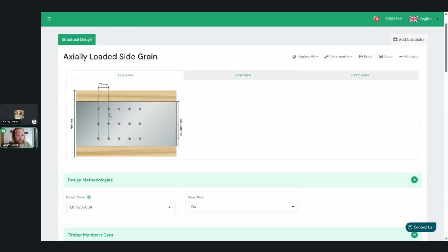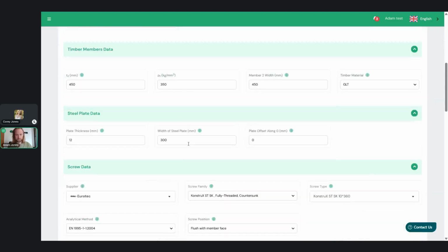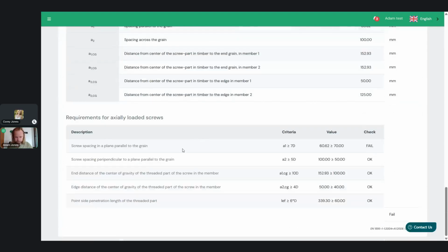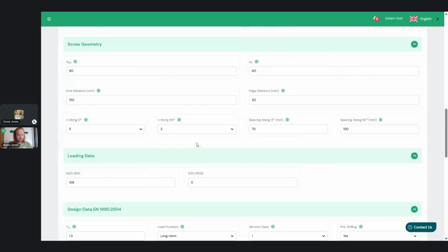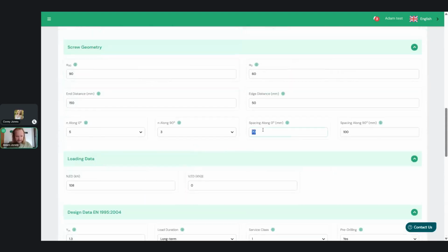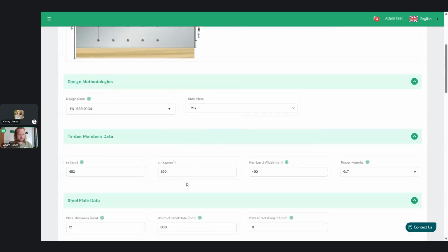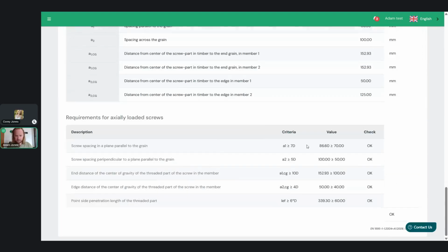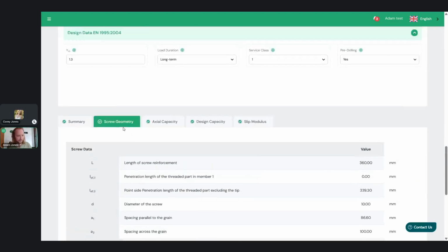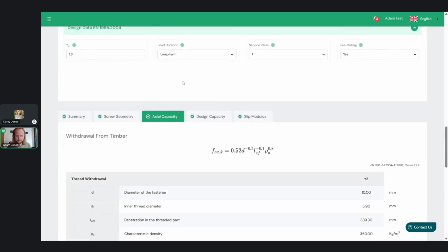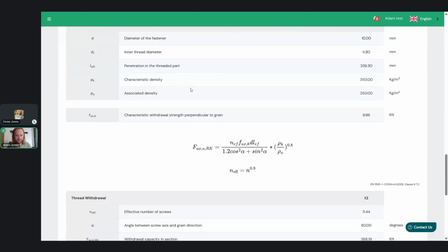If you go to the top view, you're going to have greater spacing there as well. So I updated that. I think as it's inclined, it is taking into account that as well. So if we go 100 mil, you can have increased spacing, and then now we're checking OK, which is good. It's always embarrassing and high pressure in a webinar when you're looking for the actual geometries to get the design right.